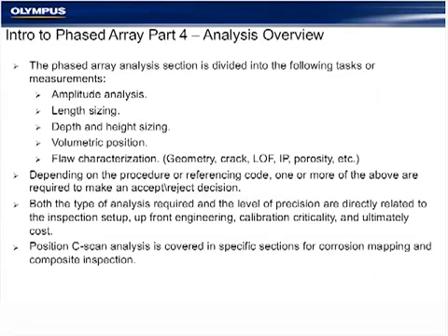That was done using a Weld Rover automated scanner that doesn't require a laptop. It's just simply a handheld paddle that goes forward and backward at a fixed position. It had a laser that was walking on the weld line that allowed me to guide it while I was looking at the OmniScan periodically. Good couplant, good probe position, everything tight, all of the probe feet adjusted correctly so that we have a good gain sensitivity on both sides of the weld. All of those things are essential for good acquisition.